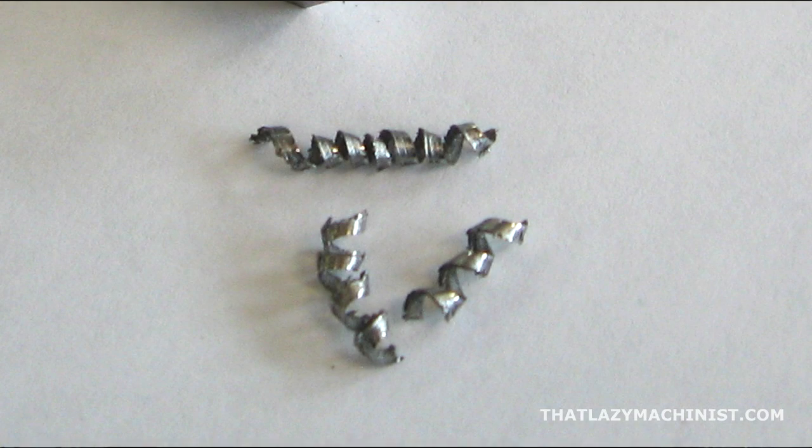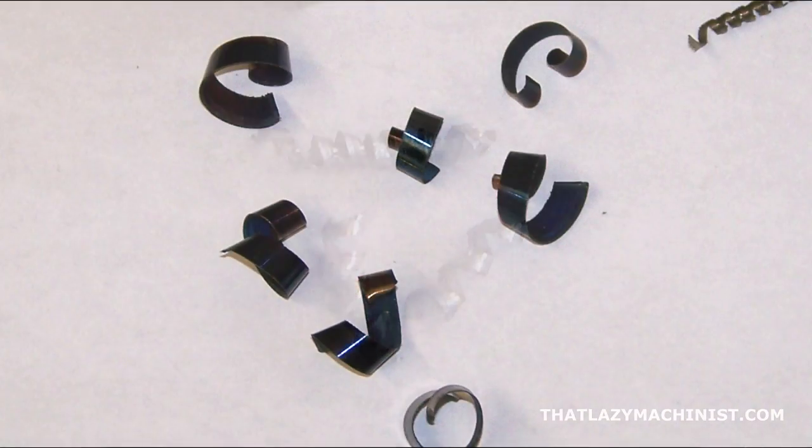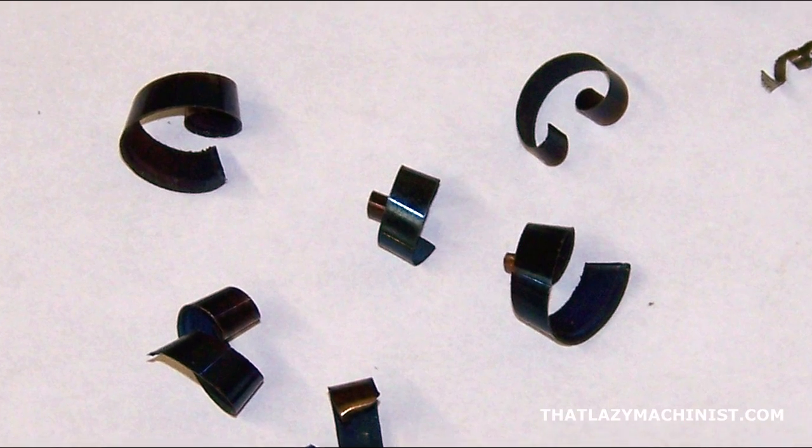Now, the color of the chips and thusly the temperature of those chips is very important. As we know, steel's malleability and ductility increases with temperature. So it's important that we have our steel chips as hot as they can be to be able to make the steel flow up the face of the tool during the next phase, which is formation.